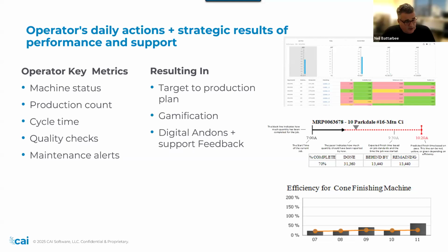And the bit that you didn't touch on there, so I'll add to it, is if those KPIs are not being met, if the cycle time to standard is not being met, or there's a stop loss event due to scrap reporting, then any good solution should have that digital andon process and escalation process to get the support team in. Don't put it all on the operator running the machine. Make sure they can get access to maintenance, to automation, to supervision, to quality, to resolve any KPIs that are not being met and get them back on track.